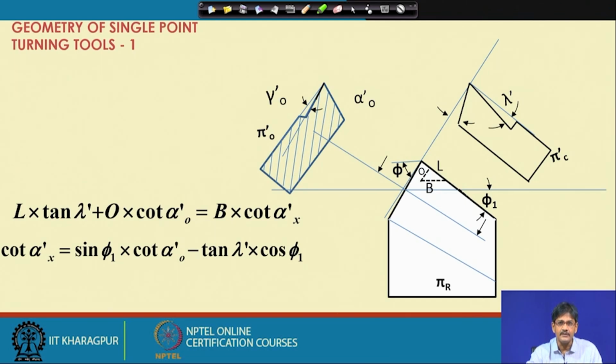That is because generally the materials which make up the tools, they are strong in compression and they are weak in tension. Okay. So, in that case, if we apply tension, they will break very easily. If you use positive rake, it can be shown that they are likely to develop tensile stresses inside them by bending as a beam. This we will be discussing later on.